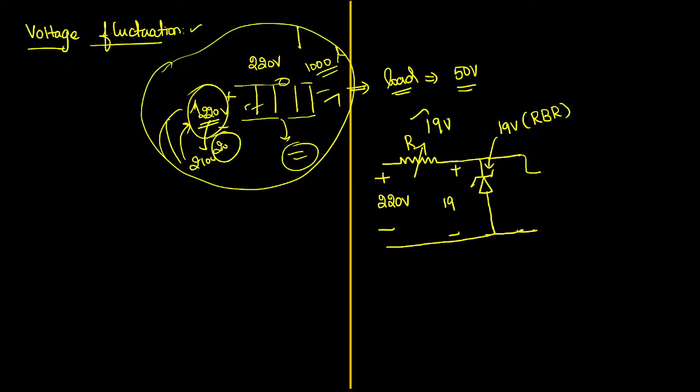So here I am going to give the connection to our laptop. What do we have to do here? So this is our laptop port. How much voltage should be injected into this? Only 19 volts I am demanding. So the moment the voltage is received here, automatically we are receiving 19 volts, so this Zener diode will turn on in the reverse breakdown region only.